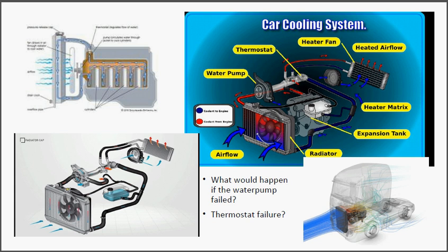Okay, the answer is the temperature of the water. It's for a car thermostat. How shall I describe it? It looks a little bit like a valve, which has got some sort of bimetallic coil, and the coil expands and presses against a flange, and if it does it, there's very little water which can go through the circuit, and if it gets too hot, then it opens up and it allows a lot of water to flow through. So that's pretty much the way it works. It's just a little mechanical device.